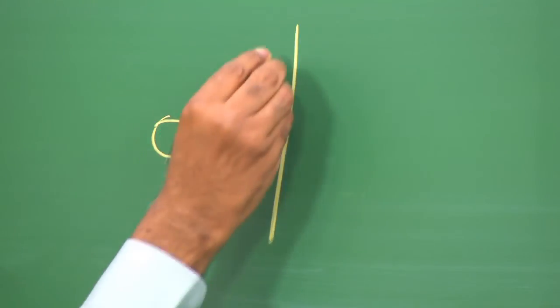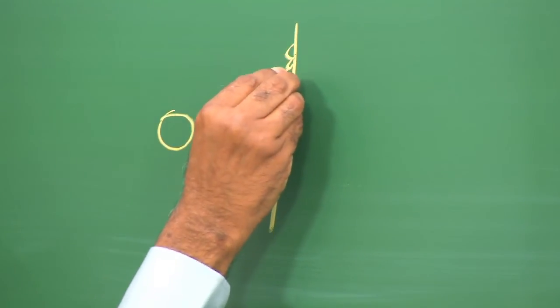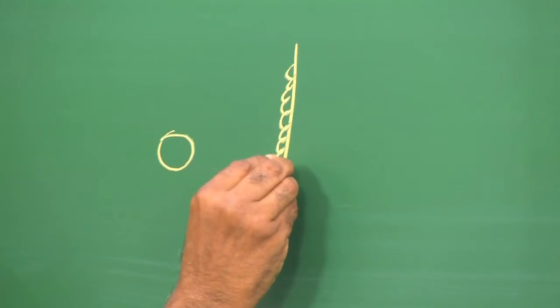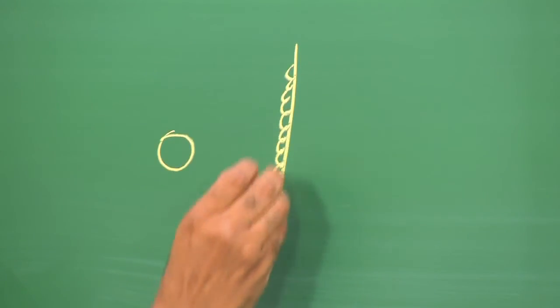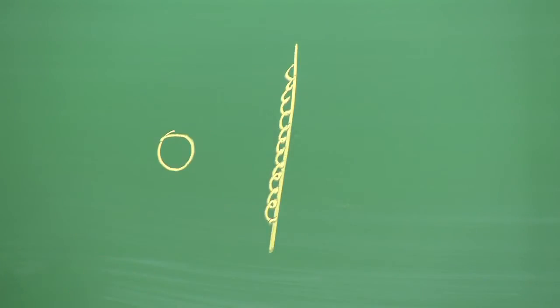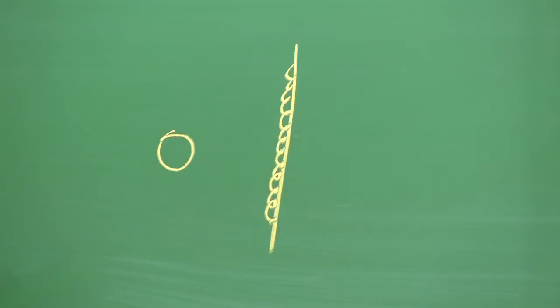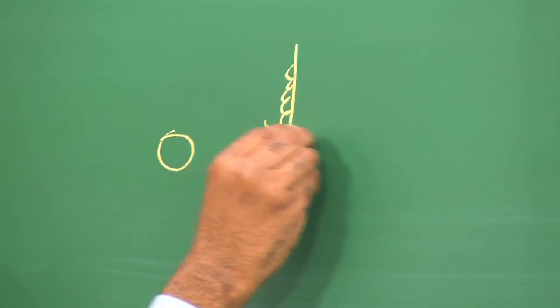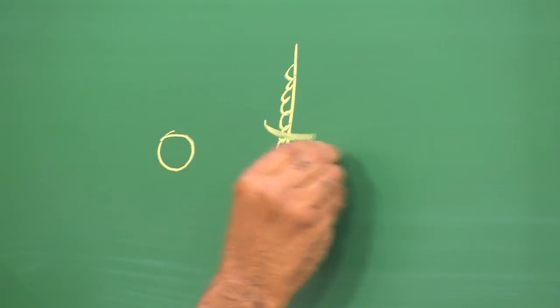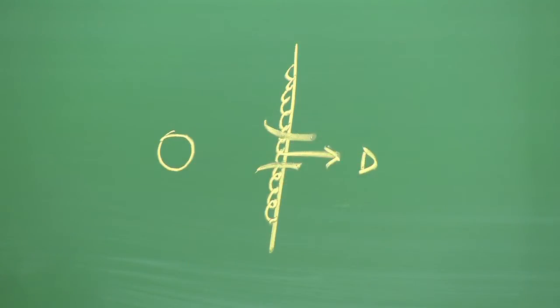If the shock wave is sufficiently strong, the chemical reactions which occur behind the hot zone of the shock wave... there is a temperature increase in the shock wave, and if this temperature increase is quite large, corresponding to the large Mach number, these chemical reactions will drive the shock wave and you get a detonation wave.